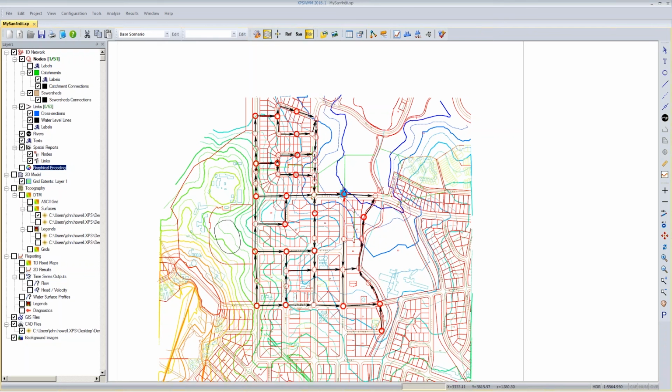inaccuracies in the data. Let's say there's an arbitrary measurement of the length from one manhole to the other. Well, what if that conduit has a really large change in elevation? They may underestimate the length of that conduit. With a geospatial platform like a commercial modeling platform, everything is geo-referenced when we bring it in. So from a bird's eye view, as long as we have the distances specified properly, since this is geo-referenced, the software now knows exactly how long this pipe is. It knows the distance between these two junctions in the system.